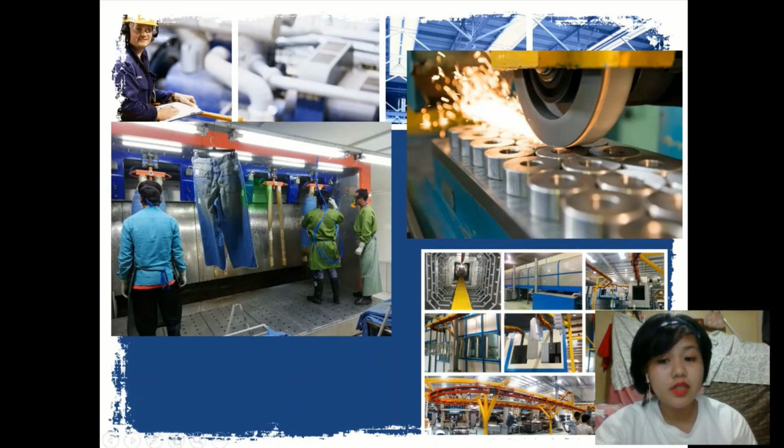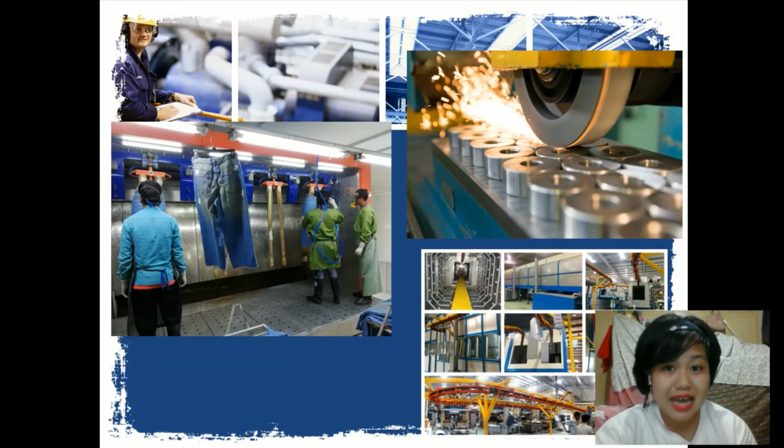Material from garment washing, metal finishing, and surface coating industries usually contains low amounts of dissolved organic content. Low amounts of dissolved organic contents are mixed with sewage to optimize the nutrient supply to the biomass acting on the wastewater. The biological systems need to have optimum biomass to form settleable flocs to enable them to be removed by settling.